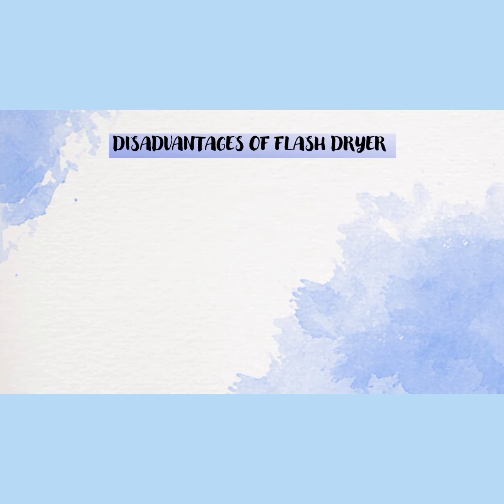On the other hand, the capital costs are low in comparison with other types of dryers. In addition, simultaneous drying and transportation is useful for materials handling process. The circulation of the material is utilized to reduce the drying time. In this instance, the number of cycles for various particles may differ, and as a result, the particles' residence duration will differ.